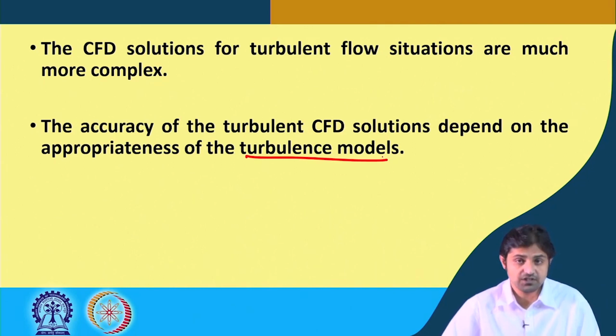In the Reynolds averaged Navier-Stokes equation, there are different turbulence models, but everything comes with a cost. Direct numerical simulation, although it has the best accuracy, requires an extremely high computation time.